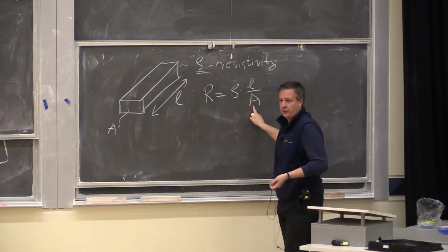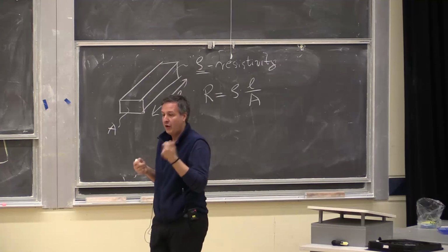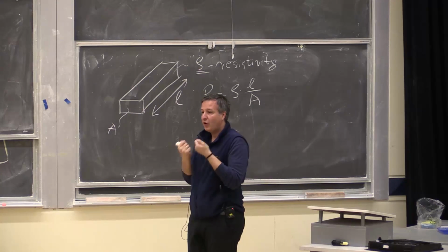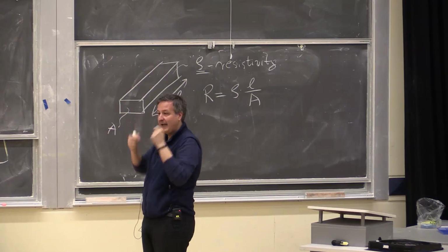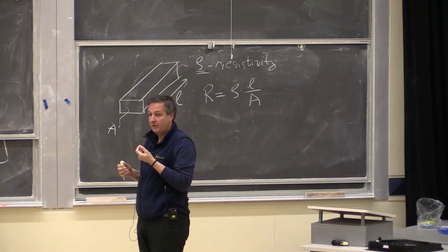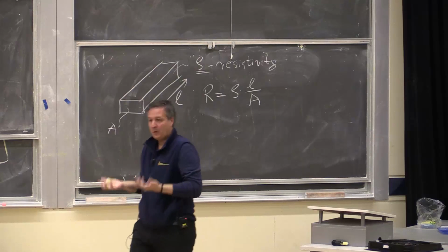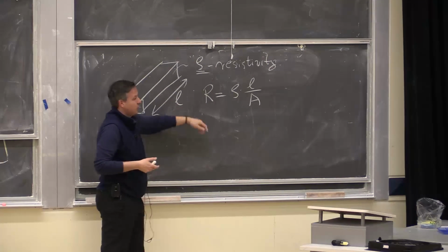And if it loses the energy, it will heat up that wire. The smaller the cross-section, again, more likely for the electron to basically go and hit something in that cross-section. Think about it this way. If I have a constant number of electrons that are flying in, and I have this huge cross-section, the density of these electrons per unit area will be smaller. But the number of atoms in the wire will be the same in that cross-section. So the likelihood that I'm going to hit an atom is less. If the cross-section is larger, with the same amount of charge, I have less likelihood to hit something, so I can just cruise through. Right? That's why with increased area, the resistance will go down.